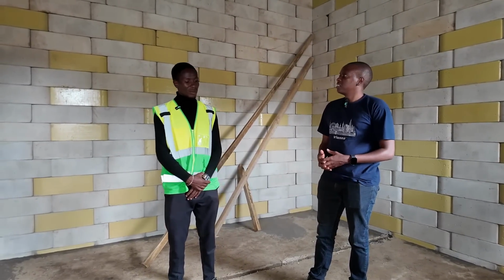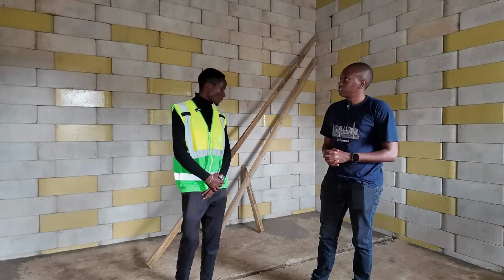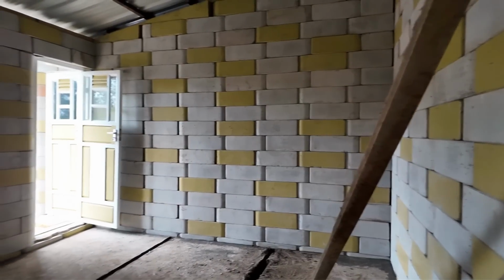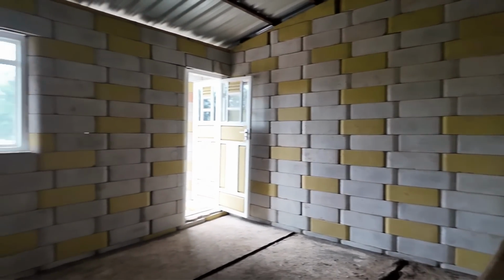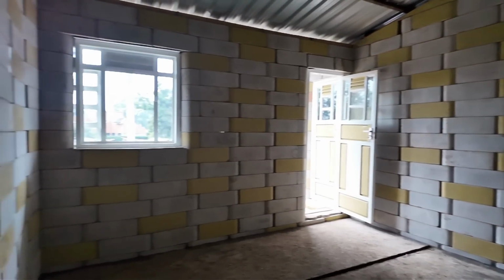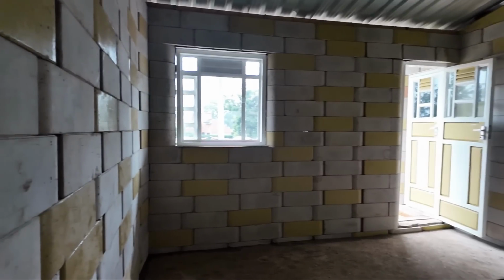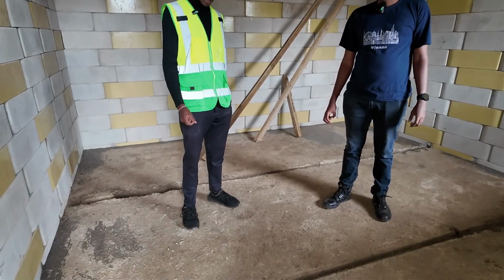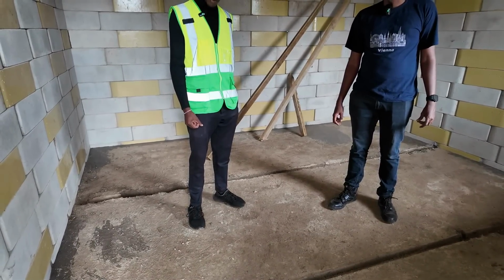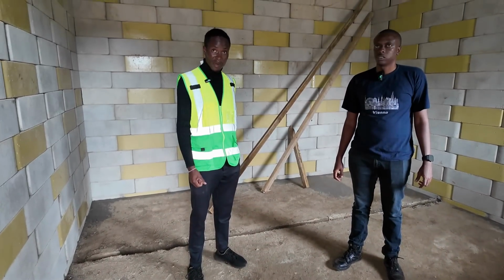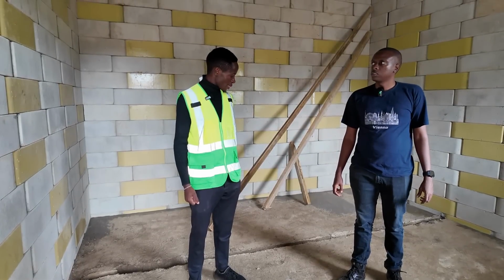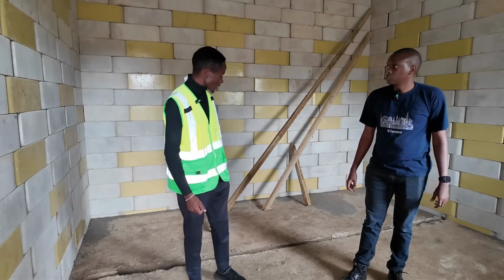Okay. So this room is also 16 square meters in terms of area. It sits right on top of the bedsitter, as you mentioned, and the floor itself is to be concreted, to be finished with a nice screed atop of it. The concrete slab that is cast atop of the marine board is around 50 mm. So it's a very thin concrete slab, and what is remaining is just a simple finish.